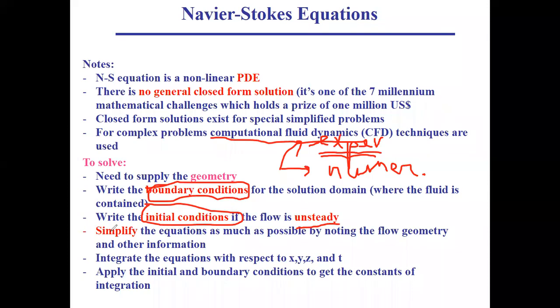If not, if your fluid can be treated as incompressible, then there is no buoyancy effect. You can have other forces that will act on your system. So pressure forces will be more important, let's say viscous forces will be more important. So you can simplify, if you want, by neglecting negligible forces when we are dealing with the momentum equation.